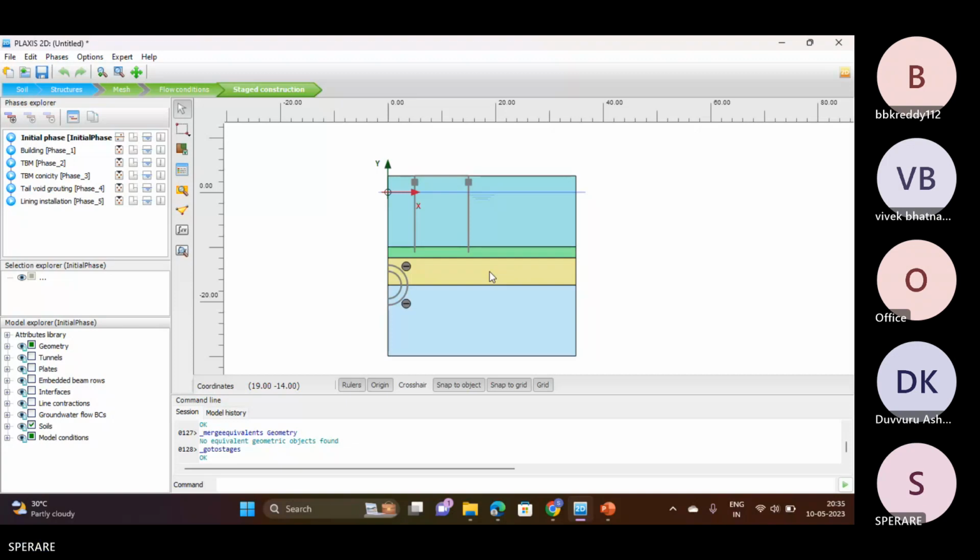So it's a pre-stress embedded in the soil that will be considered. If you go for a gravity loading, it's just about the weight due to gravity, how much weight you are building up. Only that particular weight management it will do. So tip for the day: try to analyze the problem to an extent with the K0 procedure. If not, then you go with a gravity loading. That's why the default procedure we can say is the K0 procedure as well.